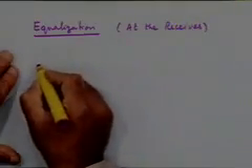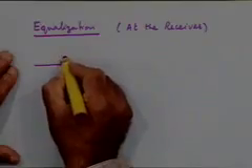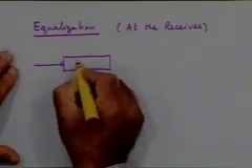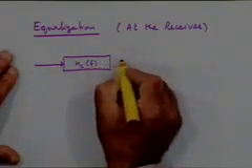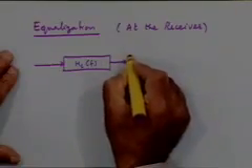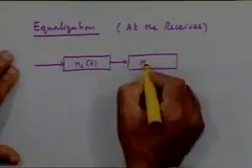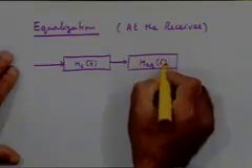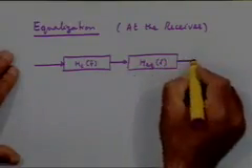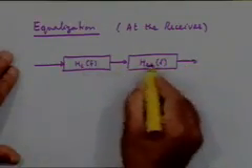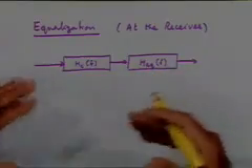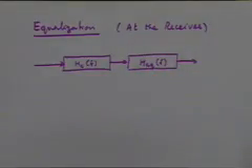So what we are saying is the message signal goes through a channel with a transfer function H_C(f). What we must do at the receiver is have a filter with transfer function, let's say H_EQ(f), where the product of these two together appears as a distortionless channel, right?